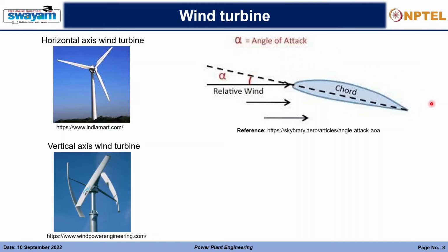Otherwise there will be a reduction in the mass flow at each side. So that is why the air particles which have diverged in the upward direction, since they have a larger distance to travel, will have to move a little quicker to reach this point at the same time. So the velocity in this curved region is increasing, it is higher compared to here, right? Due to the conservation of mass.